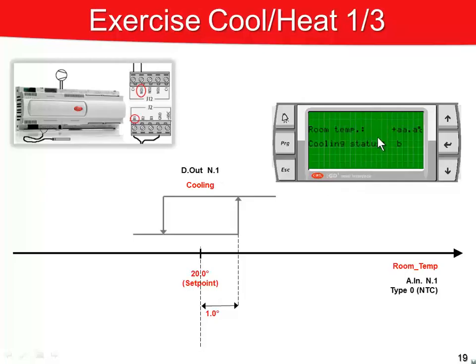Regarding the user interface, we will use a terminal with a PGD1 display which has 8 rows and 22 columns, and we will show a description of the values that we will show, and beside the value of temperature and the status of the cooling.